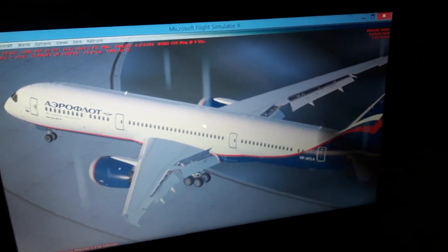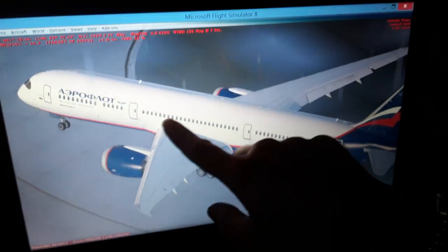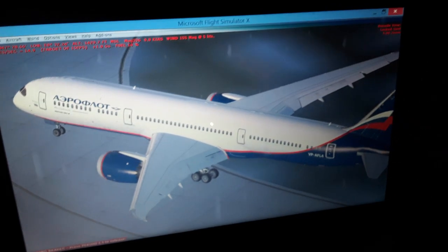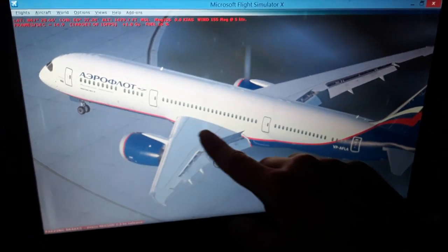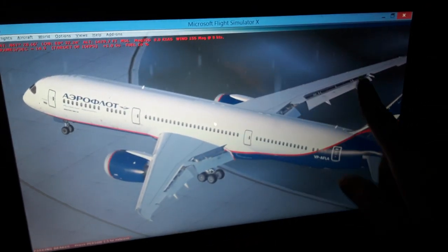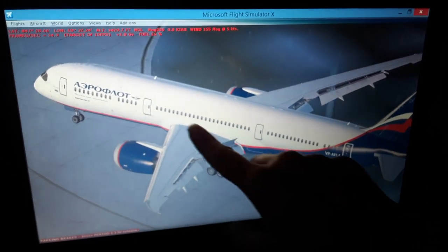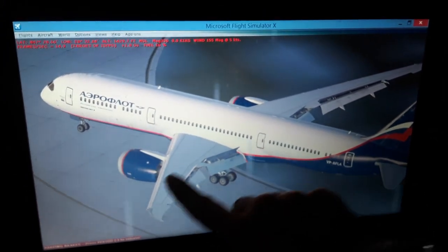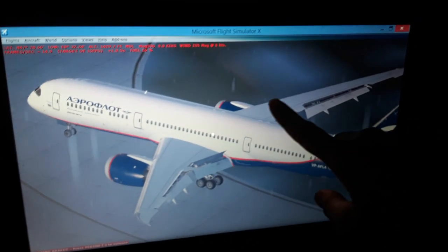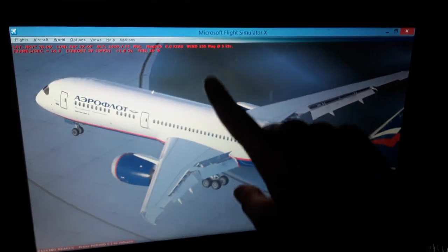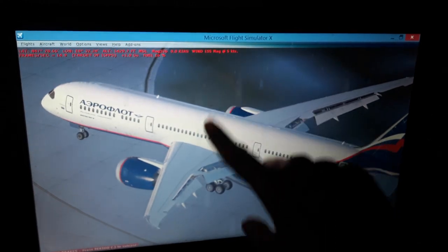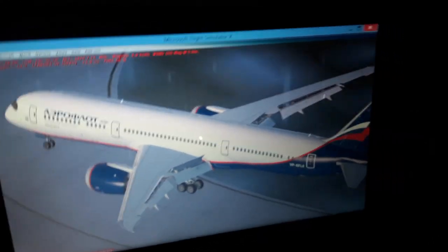The airflow becomes detached from the top surface of the wings as we fly all the way back, so the aircraft might fall if we stall it, so we need to avoid the stall for a given angle of attack and airspeed. Also we have the center of pressure that can move forward or aft. The aerodynamic chord is also the position where the center of gravity of the aircraft traverses over here.